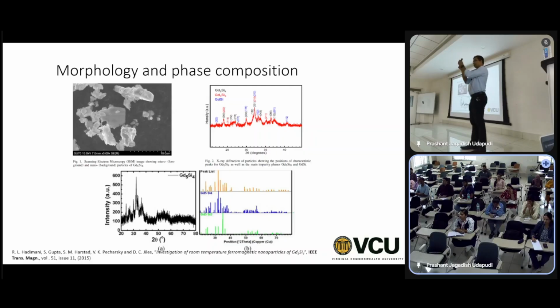You use electromagnetic coils to focus and accelerate those electrons, and when these accelerated electrons hit the sample, a lot of them are reflected back from the nucleus of the material, and some of them are reflected from the surface. Some go to 2 nanometers depth, some go to 15 nanometers depth. Depending on how deep they go, you get different types of scattered electrons.